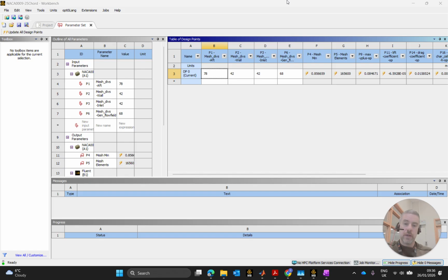So that's what mesh independence is about. It's not just about saying, yes, this is the level of refinement I need. That is something you want to find out, but that's only going to work for a certain set of physics, providing that the physics don't change and that what's being experienced in one cell is equivalent to what's being experienced in another cell, not with respect to variable values, but the physics of the flow. Okay, so a couple of preconditions on this.